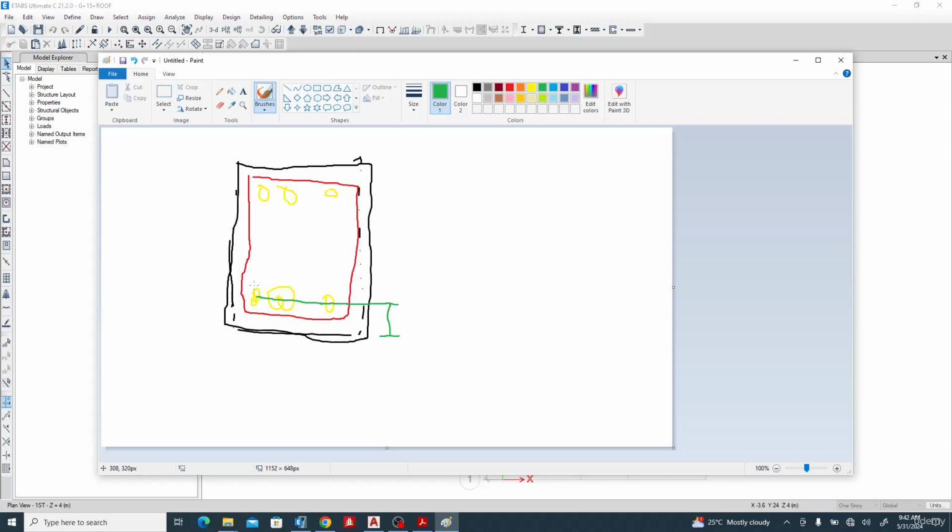That's it. But in this case, let's assume we have a spacer bar and we have something here. So you can put the centroid at this place. This is the centroid. But in most cases, we always try to have one layer of this. But in case we don't, you can always do this. It's just explanatory. So for example, from here to here is 25 mm. Now we have 25, and my stirrup is 10 mm. That is 35 already. So 25 plus 10.